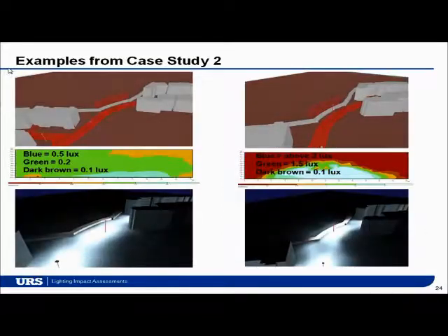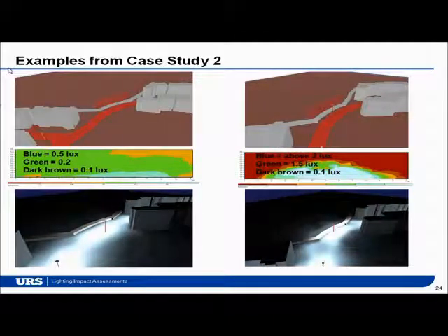But by placing the light fitting on the opposite side of the road as far away from the hedge as we could, we were able to use a narrow distribution fitting so that it would limit the light spill as much as possible. I think maybe the ecologists thought that it would be better to put the fitting closer to the hedge, facing the opposite way. But as you can see, this produces a lot of backspill. We could have used shields, but it was actually a better solution to put the fitting further from the sensitive area and use one with good control and cut-off.